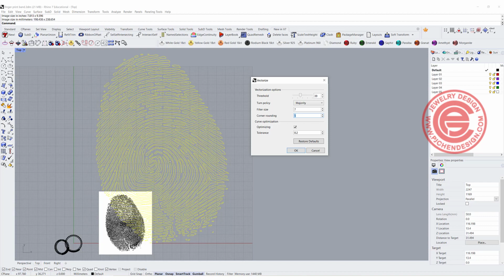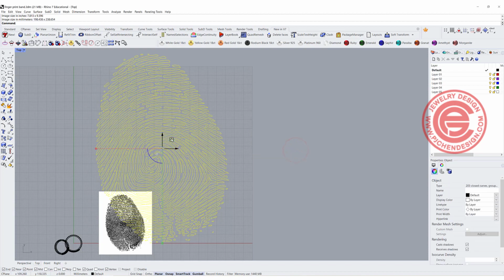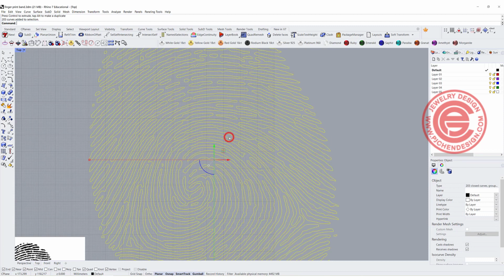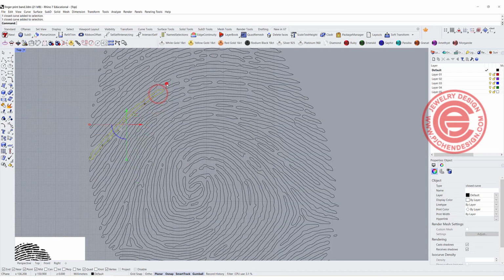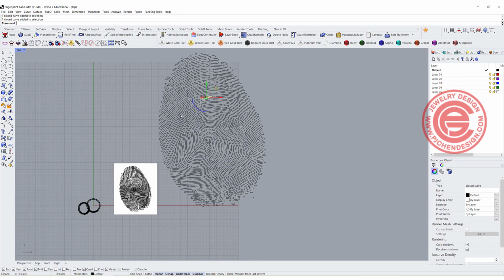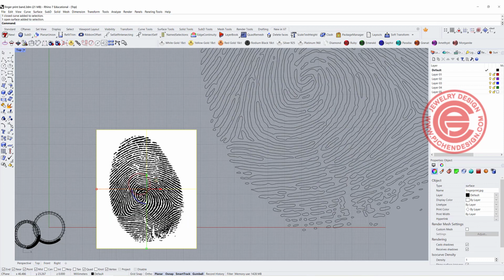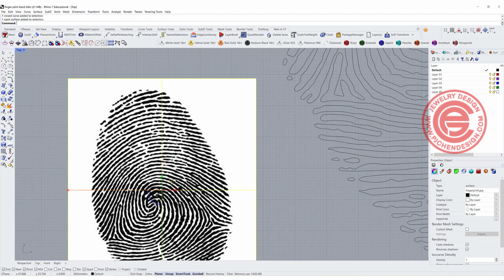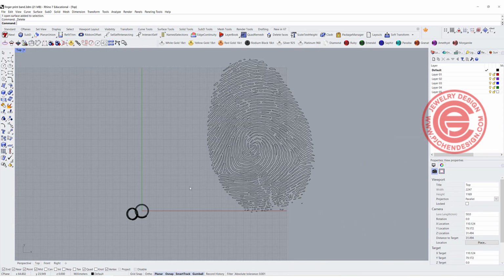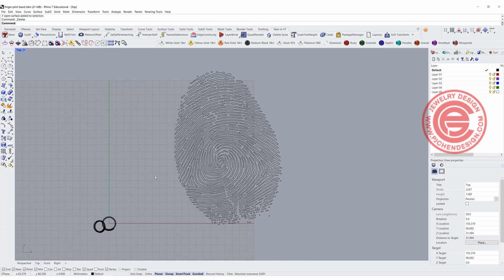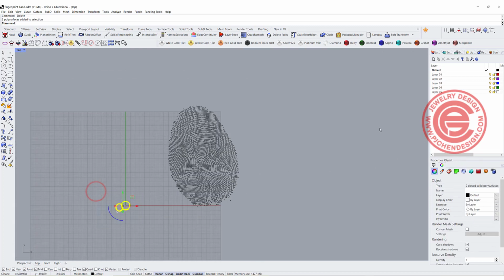Once you like the image, if you click OK, you're going to notice that if you ungroup them, they are individual closed curves, and that is what we are going to use. So instead of using the image and trying to trace over it, which is going to take forever, we want to use the Trace app or Vectorize app. Okay, so how do we work on this ring?